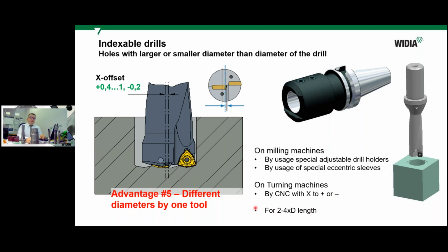Generally, it's recommended, like for turning tools, if we talk about turning, but not only these manipulations. When we need to produce a hole up to 4 diameters deep, with a longer version of the drill, 5 diameters, or for example 6 diameters, it will be a little bit complicated.